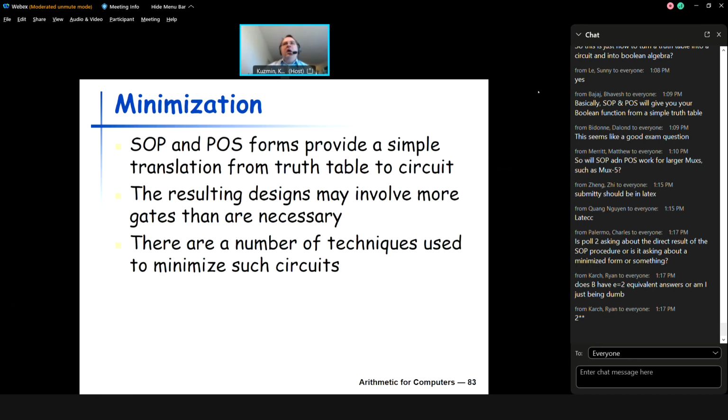So in a sense, what you do by applying laws and axioms, postulates of Boolean algebra is somewhat similar to minimization, right? Because you are applying those laws and axioms in the hope that it will make your expression simpler. And this is the same goal that you set for yourself when you use the minimization that we will discuss in a minute using K-maps or Karnaugh maps.